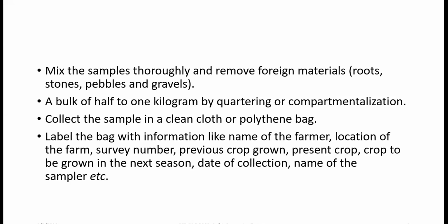0.5 to 1 kilogram is quite enough soil sample to conduct your analysis, because as you know, during preparation of the soil samples, you always take portions from the sample. In the previous procedure, you take 4 to 6 grams of soil for CEC, and for the soluble cations in your suspension, you take 10 grams to 50 ml.